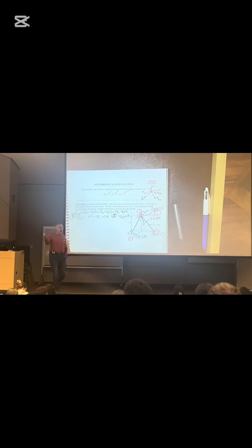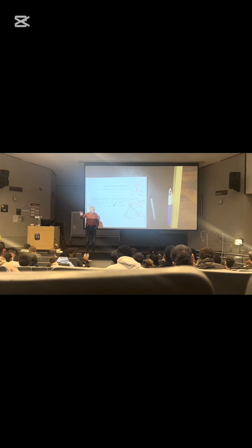Step 4 says, find me the unit vector. Take the position vector, divide by 13 to give me the unit vector, and then multiply, step 5, the force times the unit vector. Well, I'm going to do steps 4 and 5 together and say FPC vector is magnitude FPC times 4I minus 3J minus 12K, all divided by 13. That's going to give me